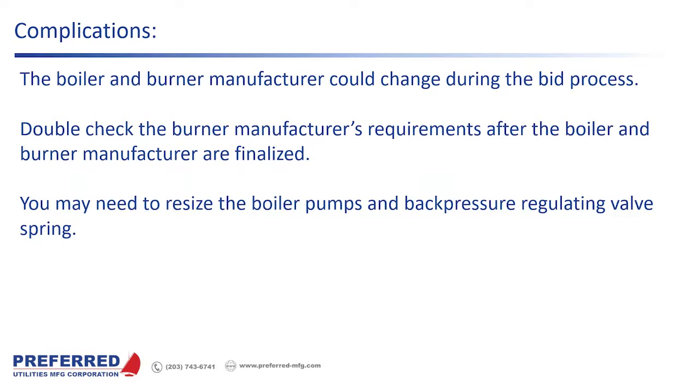And then here's a common complication. When you're dealing with new boilers or a boiler replacement project, there's going to be boilers and burners on the schedule maybe, and you're going to design the transfer piping and select the pumps and select the back pressure regulating valve. And then there's a chance that the specified or scheduled burners are not going to be what ends up getting supplied on the job.